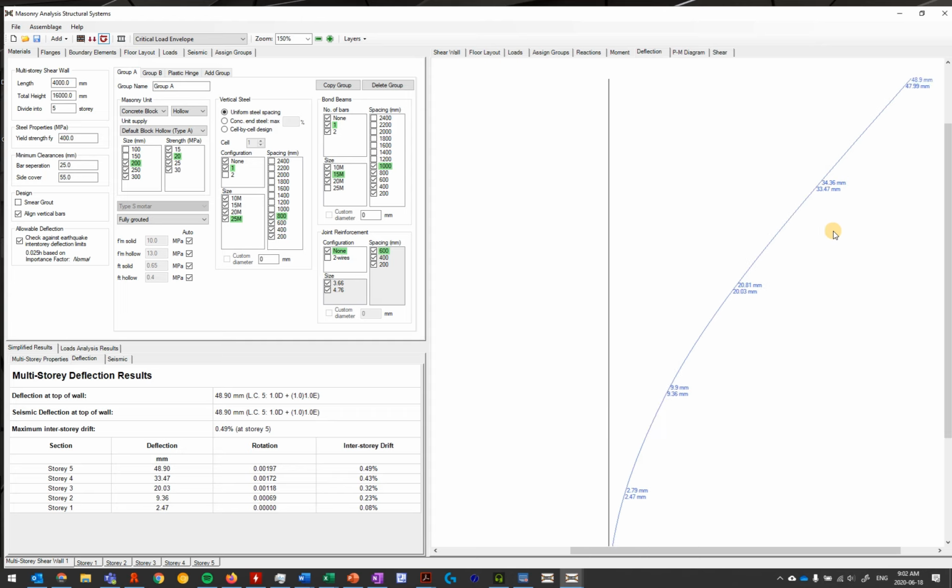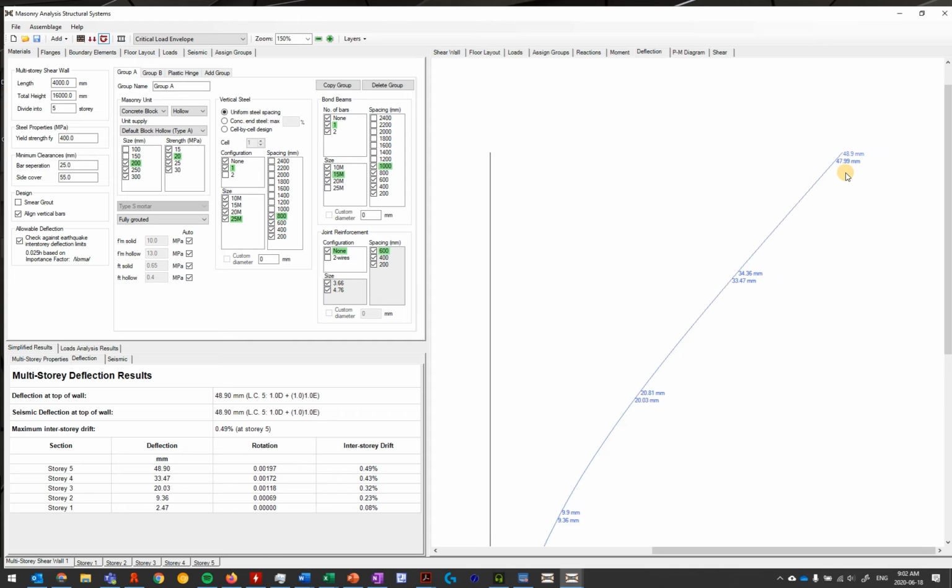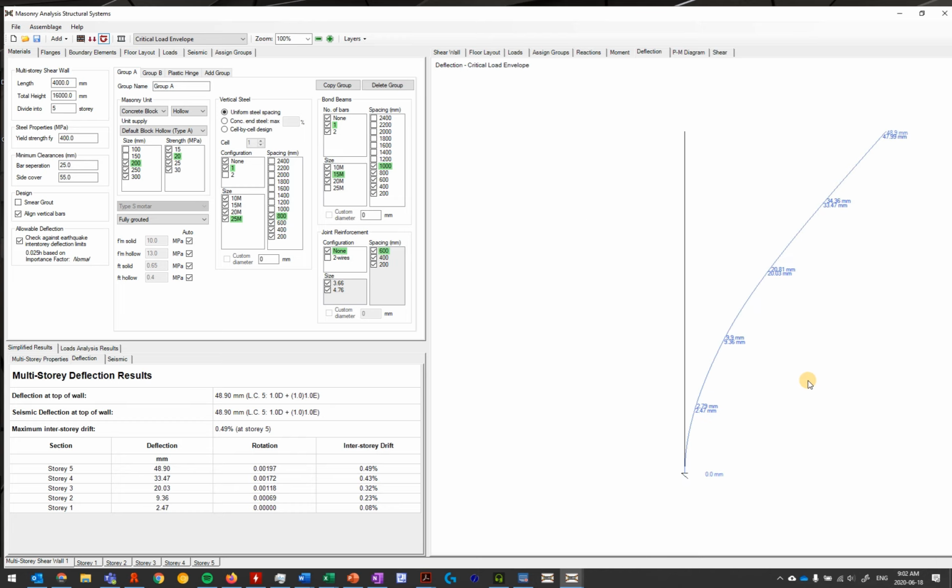These are very exaggerated. I can zoom in here. But the interstory drift is only about 20% of the maximum in this case. And with masonry structures, I find, at least in my testing, that it is fairly difficult to have issues with the drift limits without also not meeting capacity, shear, or other seismic restrictions as well.